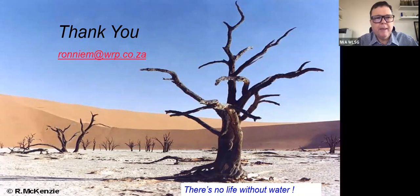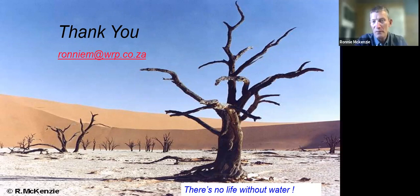I suppose it depends a lot on the head loss across the zone as well, because as you were saying, in your area the pipes are oversized, which means that doing larger zones is a lot easier. Whereas in the UK, where the pipes are probably a bit smaller, you'd have too much variable head loss across the zones, I'd have thought. I've simplified it a bit, but it's quite complicated, and in many cases the zones have been designed quite well.